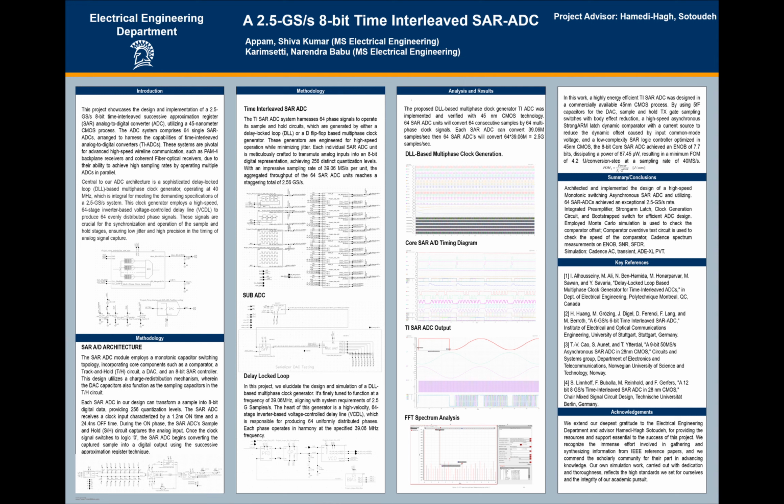We together did a 2.5 giga sample per second, 8-bit time interleaved SAR ADC under project advisor Hamediha. In this ADC we utilized a 45 nanometer CMOS technology. The ADC comprises 64 single core ADCs and harnesses the capabilities of time interleaved successive approximation analog to digital converters.